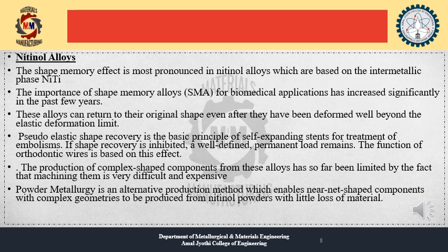Pseudoelastic shape recovery is the basic principle of self-expanding stents for treatment of embolism. If shape recovery is inhibited, a well-defined permanent load remains. The function of orthodontic wire is based on this effect. The production of complex shaped components from this alloy has so far been limited by the fact that machining them is very difficult and expensive. Powder metallurgy is an alternative production method which enables near-net shaped components with complex geometry to be produced from nitinol powder with less loss of material.